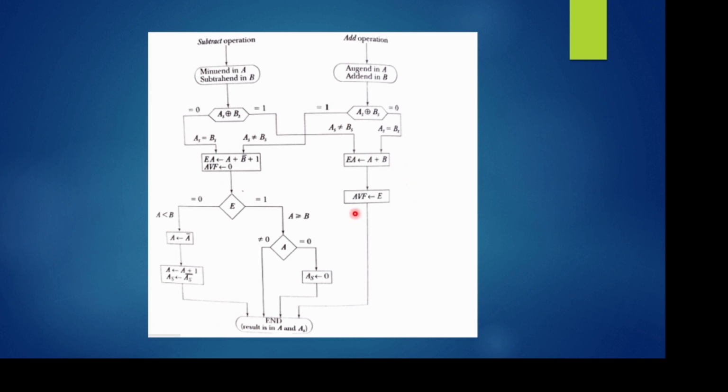Also we have an additional flip-flop for indicating overflow, the add overflow flip-flop, indicated here. Overflow means, if both the numbers are 8 bits, and an end carry is generated at the MSB point so that the resultant changes to a 9-bit value, then we can say that an overflow has occurred. That will be indicated using this flip-flop, which is also a single bit flip-flop. As we have already mentioned, if both the signs are the same, we just add the magnitudes and give the same sign, the end carry is saved in the single bit E register, and if there is an overflow, it is indicated using the add overflow flip-flop.